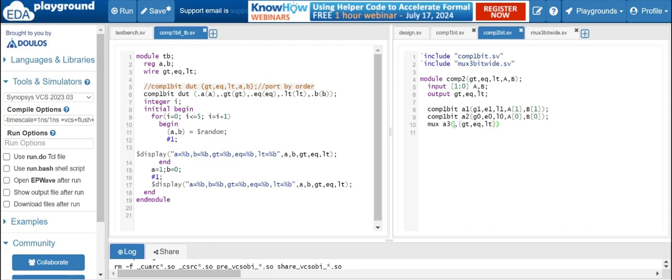So let me do it like this. Sorry. First, what is S? What is the select line here? G1, and then one of the inputs I1, that means 100. So for that we need to write 3'b100, comma. What will be the other input? The other input is the output of another multiplexer. So let us assume it as a wire, we will say y0, and then the output.